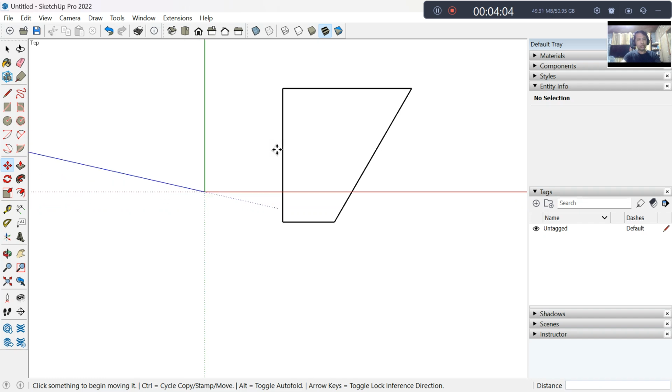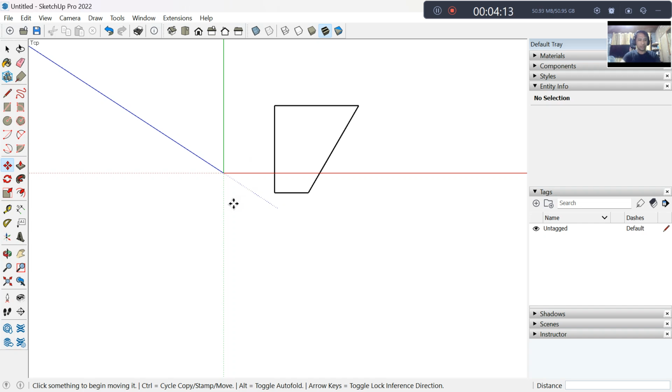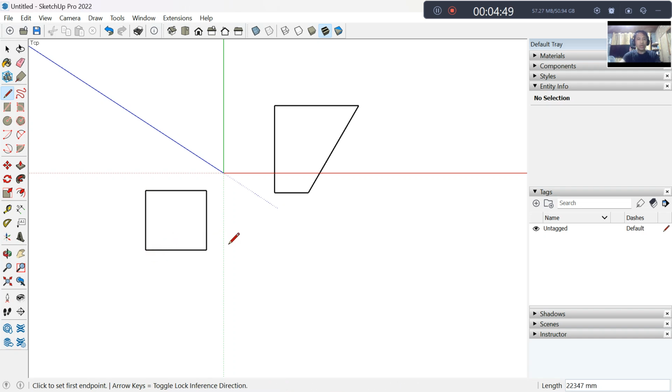In drawing, using the mouse is very essential. For example, I will draw a line. This time, I will go to the tools here, the drawing tools, or I will just type L for line. And then I will draw a line now. Left click, release, then drag, left click, release, then drag, and so on. To terminate the command, just press spacebar.